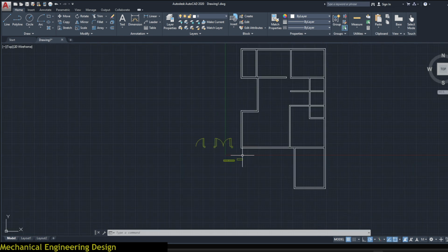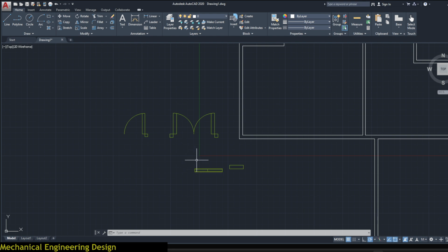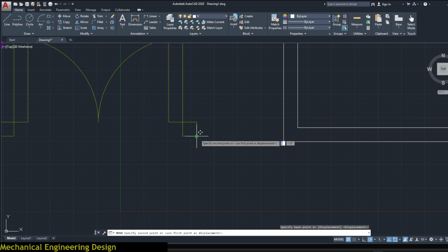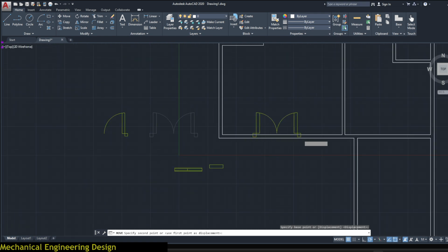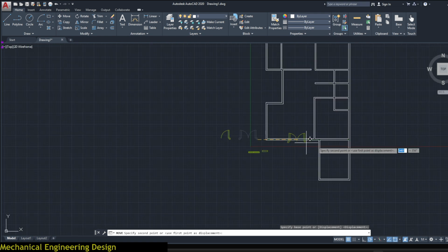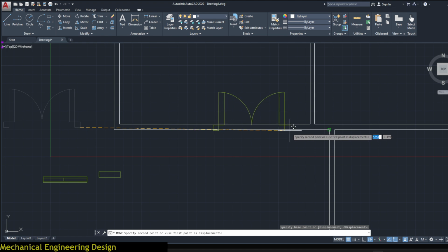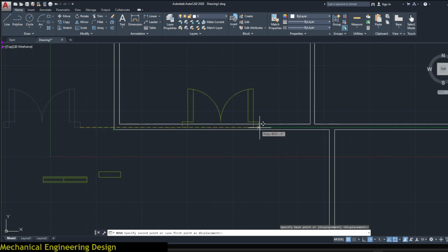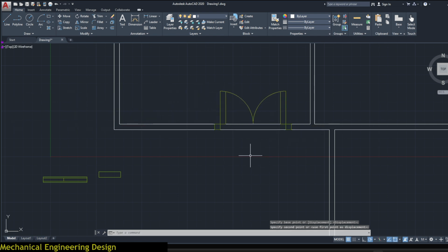Now, having designed all the blocks, we go to insert them. So you'll begin with larger door. Just move, click on this point, drag it, and we'll put it on the entrance. So just come to this point and drag it horizontally to this point, like that.